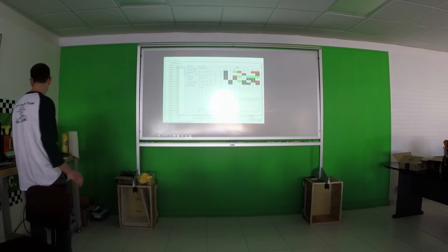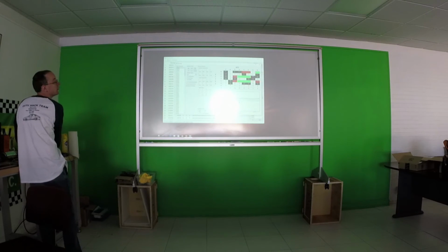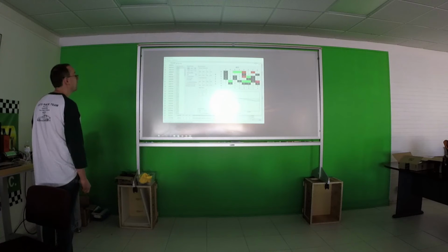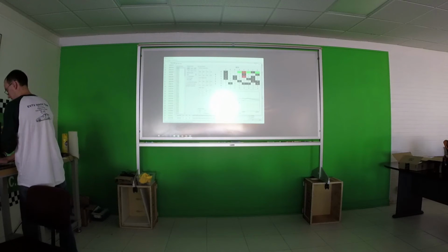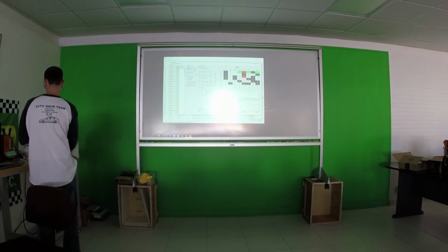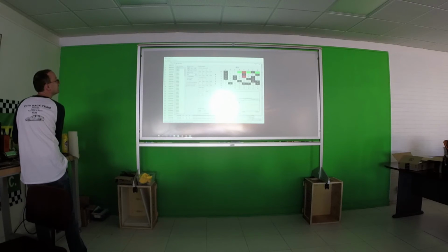So that can be used to see how the data changes over time. There's also another capability in here, trigger values. Let's say that you have a whole bunch of data and you only care when you get a certain data byte value. I'm going to play back through. I'll set that to 0xA2. Now I can speed this way up. Play it. And as soon as it hits A2 again, it stops.